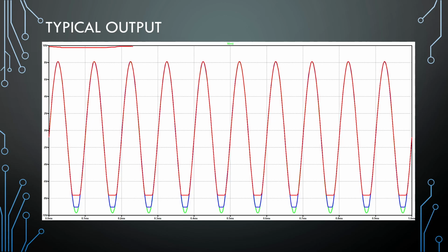So in my examples here, I'm going to use plus minus 10 volt rails. The issue comes in typically at the bottom, where it can start clipping early or a little bit later, or you can almost reach the rail. Now that's a part where the design of the Class A amplifier comes in.